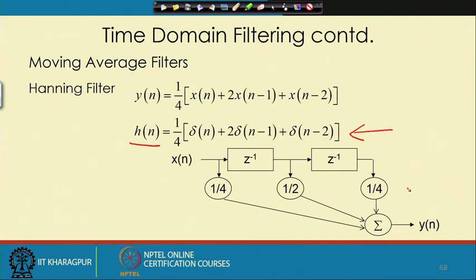But if you implement it in a computer, it is better to do it using shifting, and if you have odd values, then you may have to use multiplication. But integer multiplication is much faster, and in the case of an integer filter, that is the advantage we take to provide the result in real time and on cheaper hardware. That means we can use, say, a DSP which is an integer DSP to do this job.